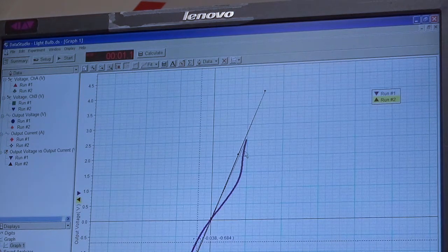So in that case, by incrementing the frequency from 0.1 up to 20 Hertz, first off, the light bulb stopped flickering, meaning that the temperature of the light bulb became steady at a very high frequency, and therefore the corresponding resistance of the light bulb also became steady, which has led to the formation of that straight line relationship between the voltage and the current, and therefore turning the light bulb into an ohmic device.